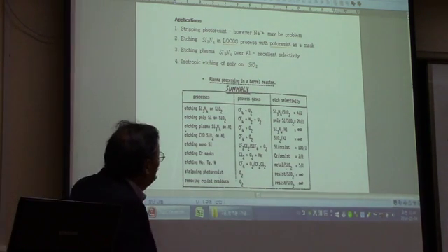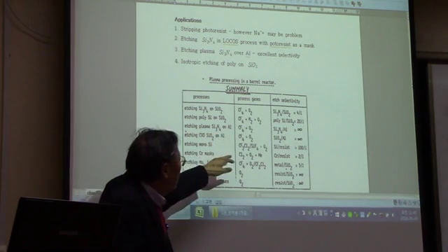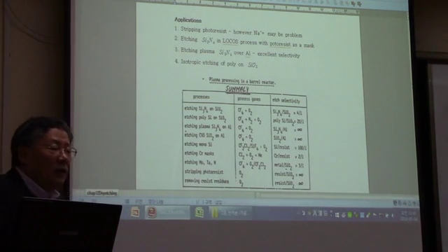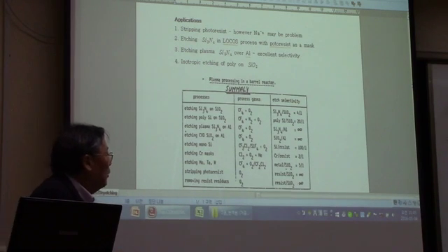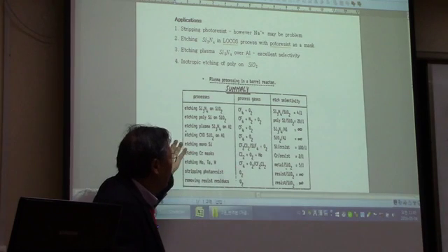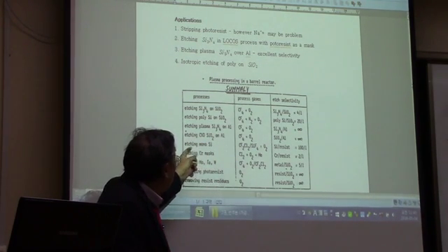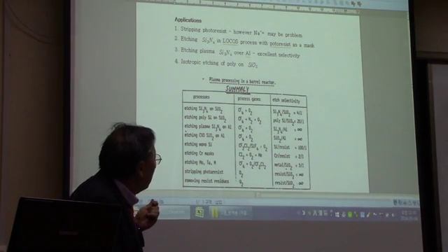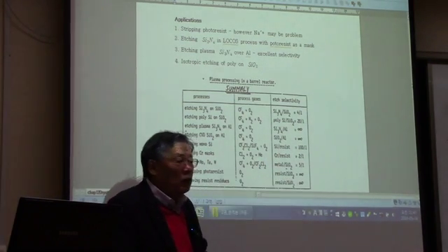Okay? That's how you read this. Etch plasma, silicon nitride, and aluminum is infinity. So you can just put it in a chamber and leave it there for a long time to complete the etch of the silicon nitride, and it is safe. Silicon oxide and aluminum, and etching silicon on the resist is 100 to 1. So the photoresist can be used as a mask.